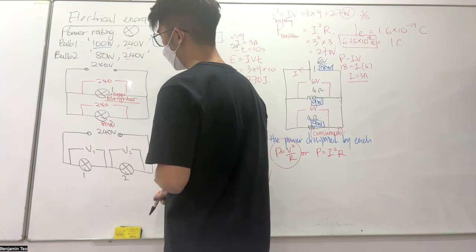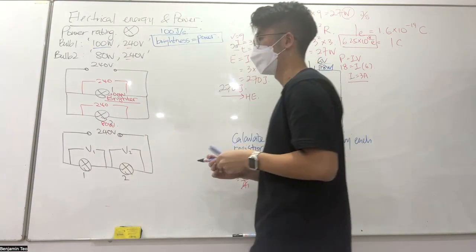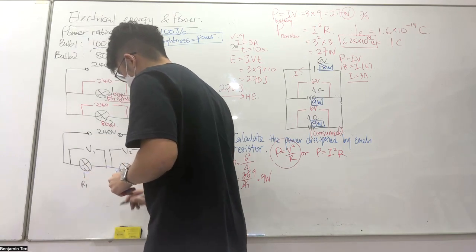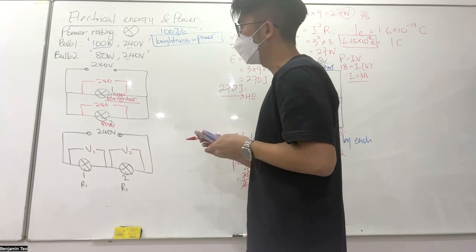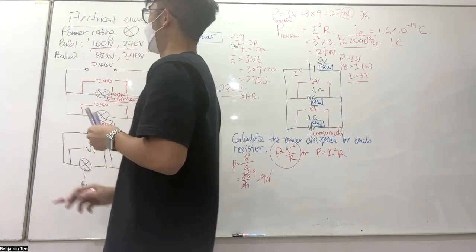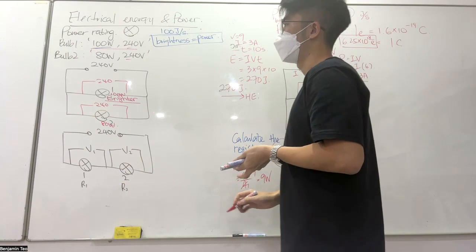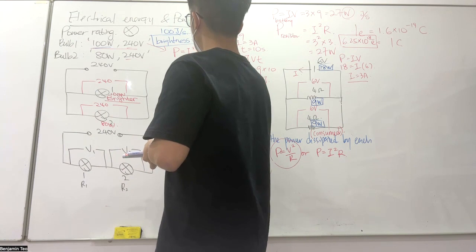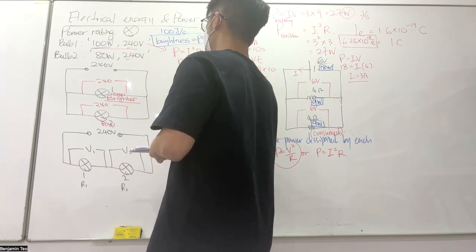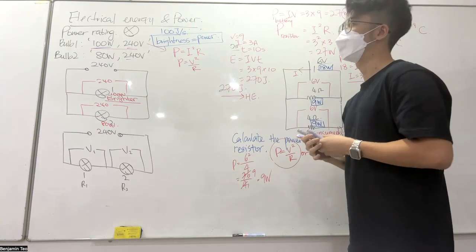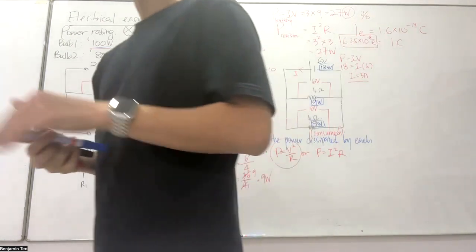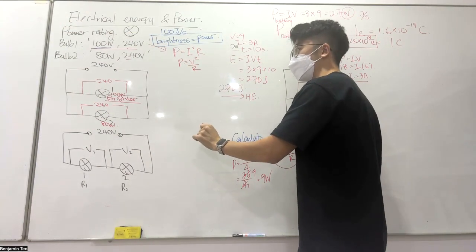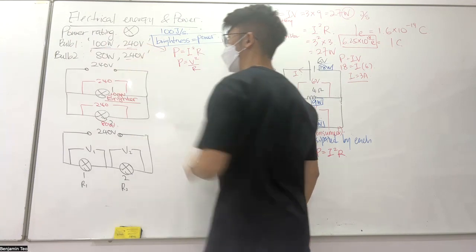To get V1 and V2, can we first find the resistance of the bulb? Because the resistance is R1 and R2. So you can find the resistance from its power rating. How? Power for a resistor is I squared R or V squared over R, right? Once you find its resistance, it is fixed and does not change.